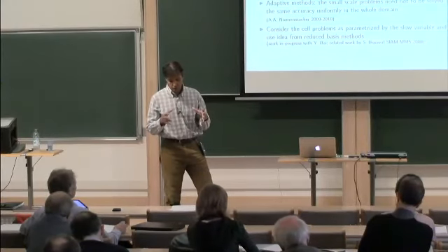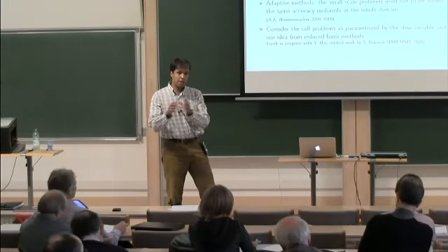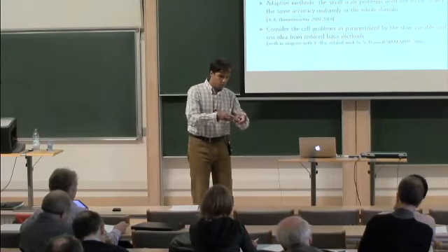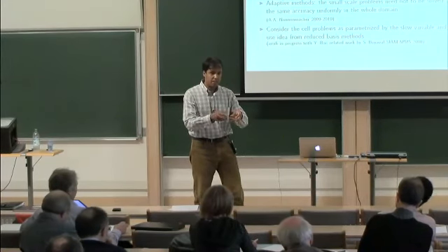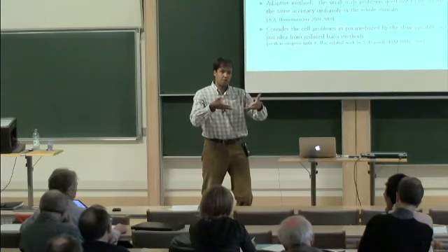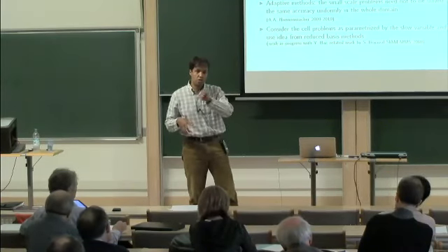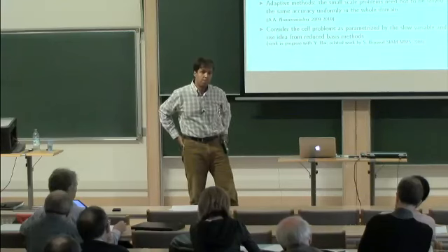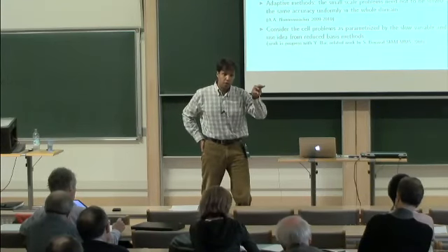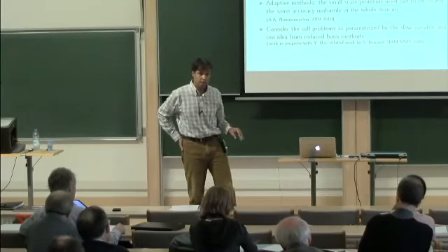When you do the FEM and you do the local assembly in each of the local elements, the contribution of the microscopic FEM in fact gives you a scaled value of the homogenized tensor. So you can just recover that in each of your sampling domains if you want, and you can have error estimates, which depend, of course, on the accuracy with which you do the finite element calculation in the micro sampling domains. Yeah, you can do that.